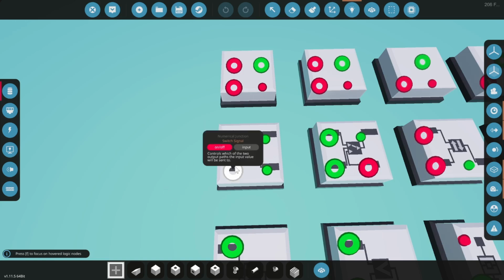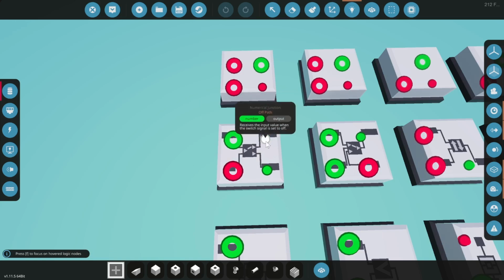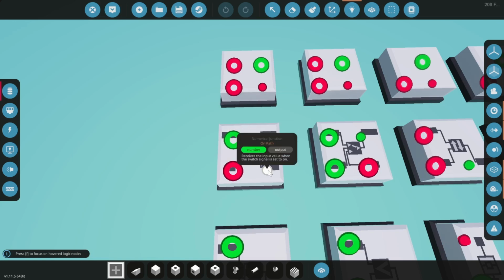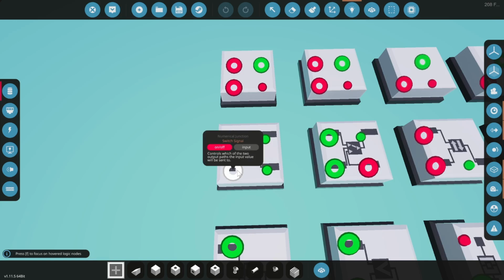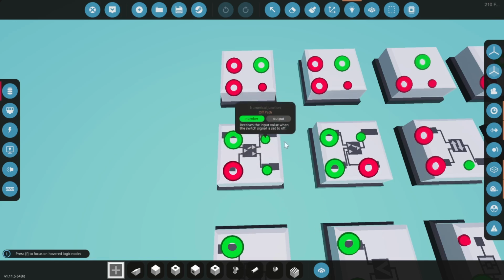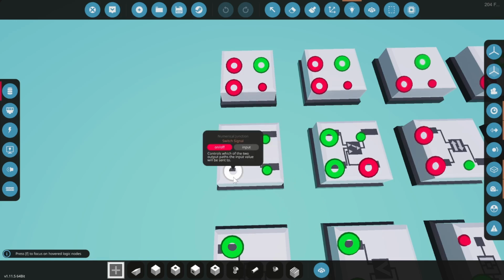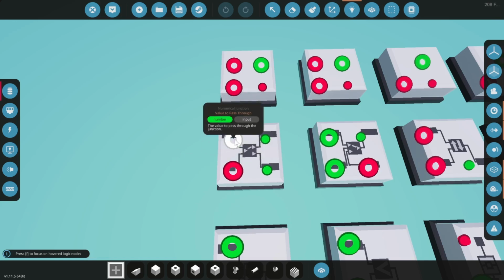Now you hit this and you set it to on, the value that's coming in here will now go through the on path, because that's on. So if you have the 5 value coming through, whatever is connected to this will now receive the value of 5. And everything that's connected here will receive the value of 0. So no value, value while on, value, no value, off. And this is the value you're wanting to bring in.